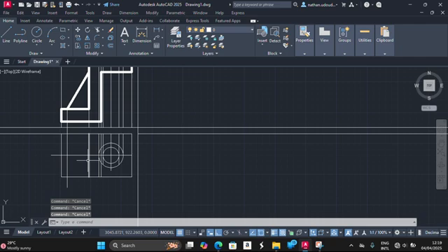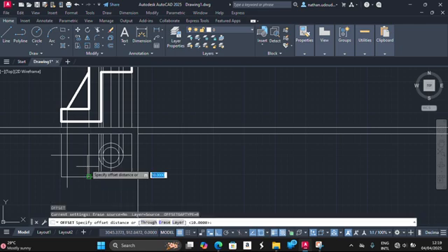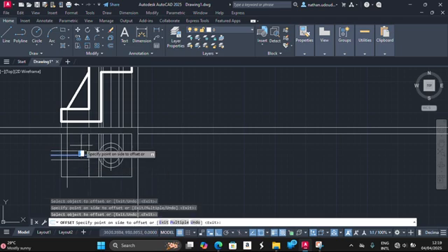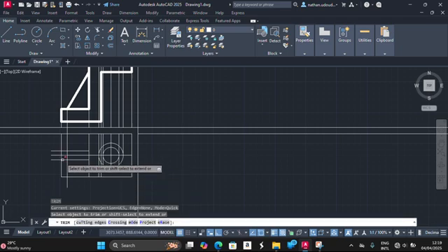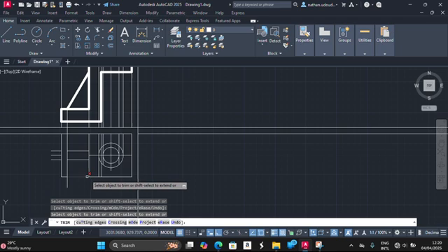So now you can offset. The wedge has a thickness of 14. So you have O, enter, 7, enter. So to the left or up and then down. So now you can pick up your trim command, TR, enter. Then you trim up this, trim up this, trim up this. You can trim up this inner one as well.